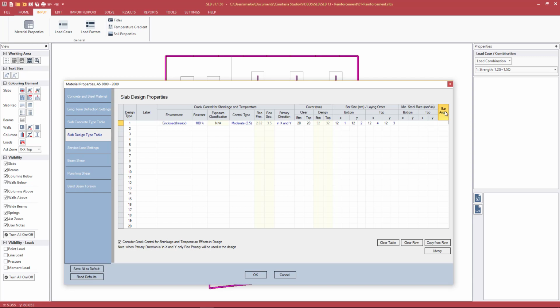What bar angle refers to is the angle at which the bending moment and then the reinforcement is designed. So if we have a section of a slab, or all of the slab, at an angle, we would specify the angle from the orthogonal, and that rotates the X and Y axis by this set angle, and then we calculate the results by that amount.